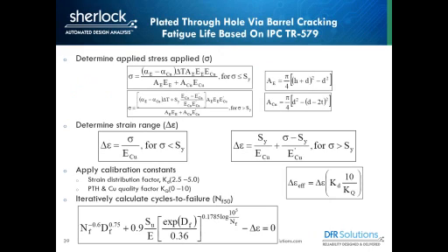Again, it's easy. If you want to spreadsheet this model up, you can do it in a spreadsheet. You can do it for a single hole, one hole at a time, and it may be sufficient to do it that way. But we have implemented it into the Sherlock tool to make it a lot easier. You can use it as a standalone tool, like I showed with the solder fatigue calculator, or I can assess all the different plated through holes on my circuit board.